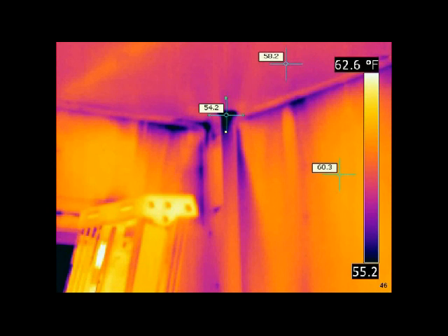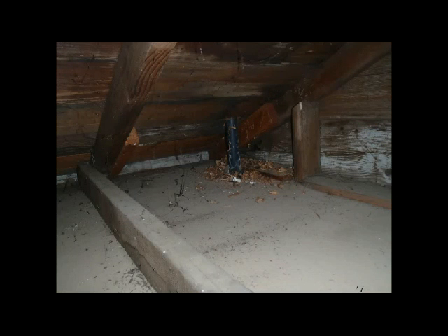So at this point, you could snap a couple of infrared images for later use, send the house doctors up to seal the air leaks if they have access to it, and then retest again if this was the main issue with your failure. If you crawled up in the attic, took a look, this is what you'd see. You'd see a plumbing vent penetrating the ceiling up into a vented attic space. So this attic space is directly to the outside, not a stitch of insulation, and some top plates. You can see maybe some leaks over by the top plates there.